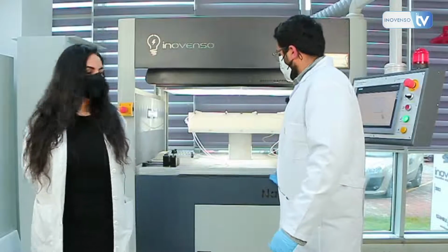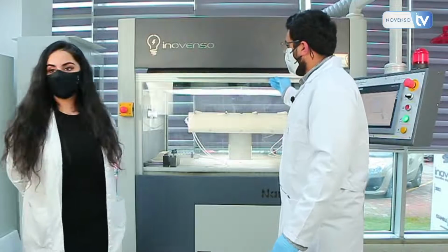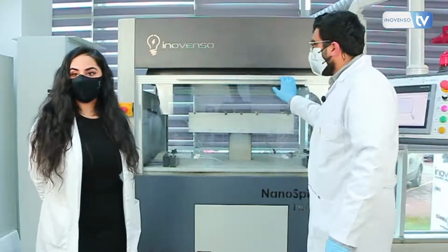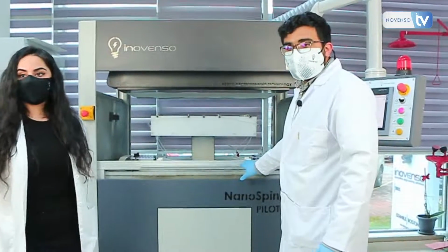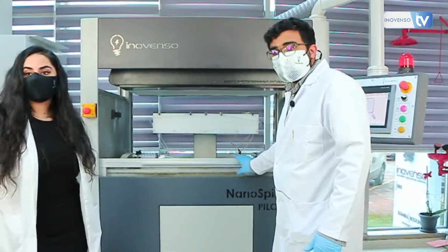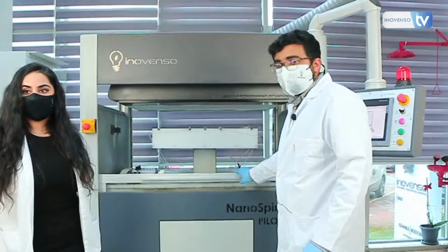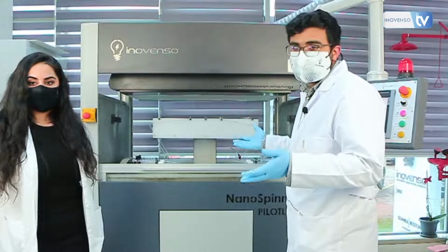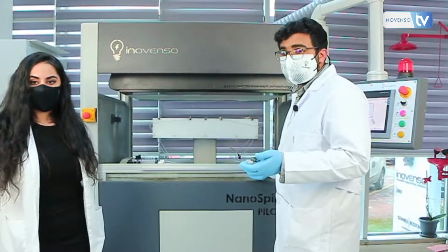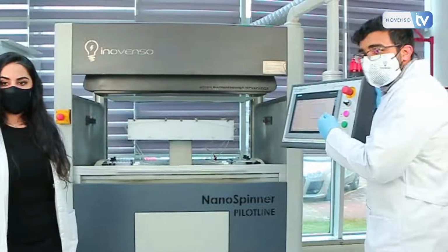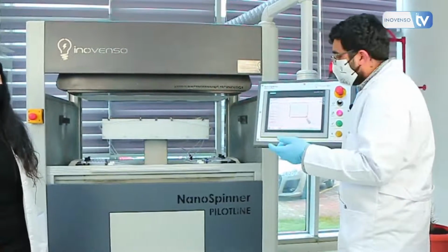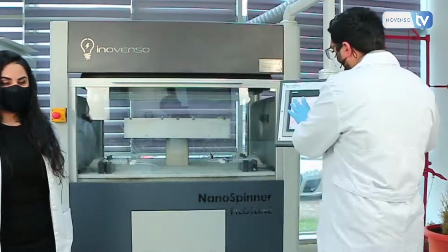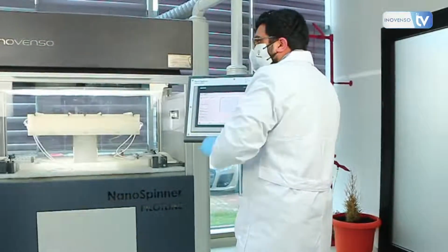Let's show you another thing. Suppose you have the safety door feature on, and you activate it. Now the machine is not going to turn on as long as this door isn't closed. It needs to be closed for it to operate, because in some cases you would want the chamber to be untampered with, so no one should access it. This machine is not going to work unless you close this properly. But for this purpose, I'm just going to unlock it, and the reset button should be working.